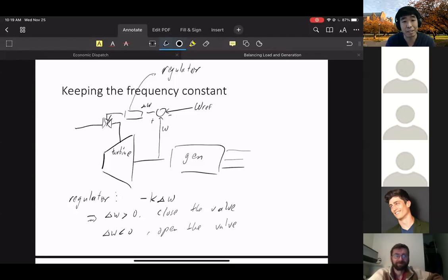For a lot of generators, we can't write down, for example, the constant K. We don't know what it is. It's just something in the feedback loop. For a lot of newer generators, it is a microcontroller. At least it's programmable, but it's not programmed very often. It comes out of the factory, somebody builds a generator, they just have some setting and it's sitting there.